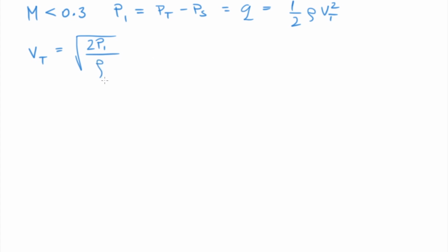Now, because of the difficulties in measuring rho, we are going to calibrate our pressure gauge, which is effectively what our airspeed indicator is, to show an indicated airspeed using an equation of this form, where rho 0 is the sea level standard value of the density.